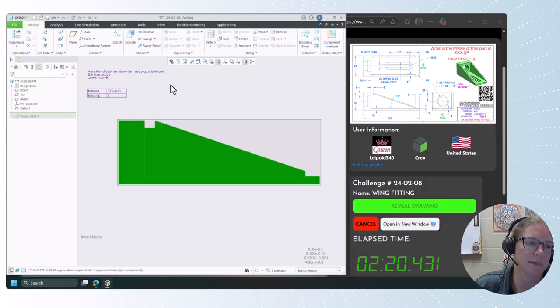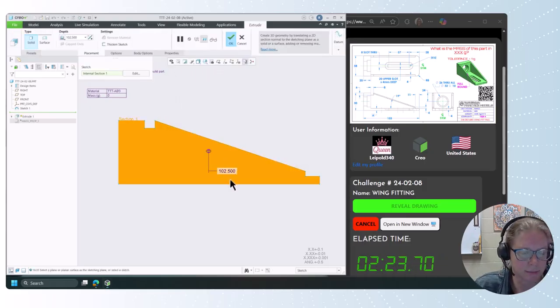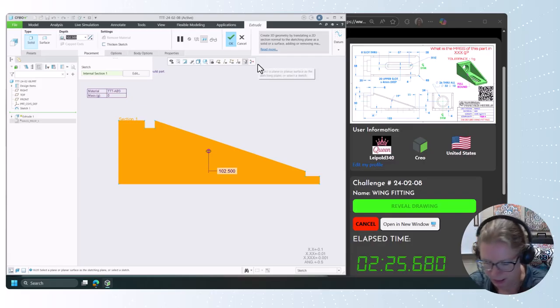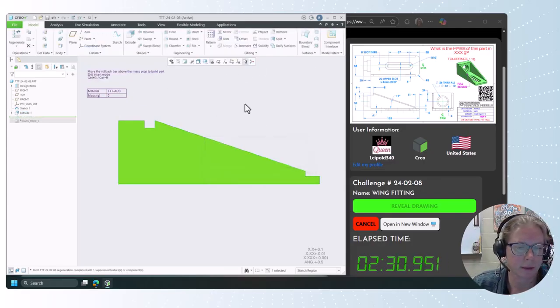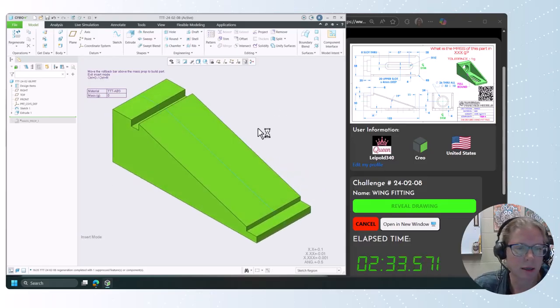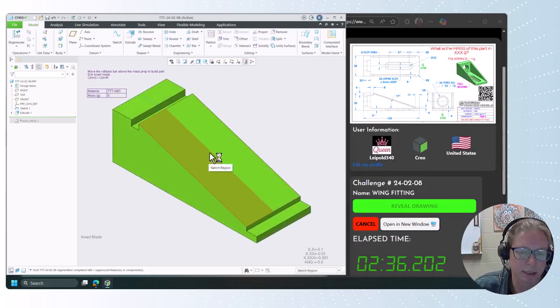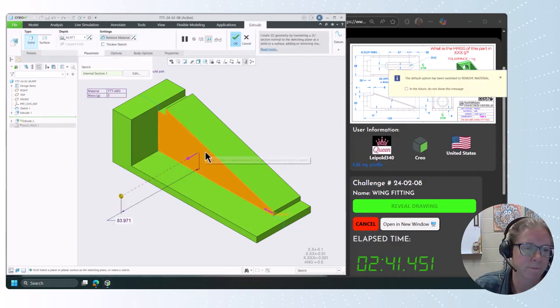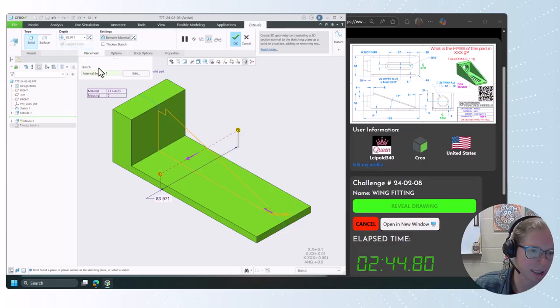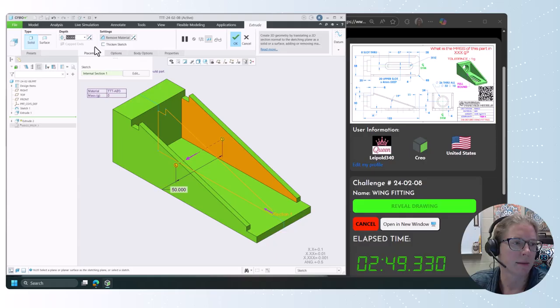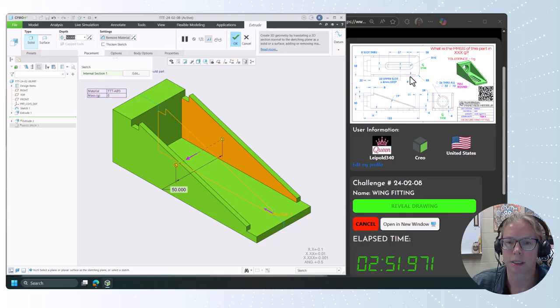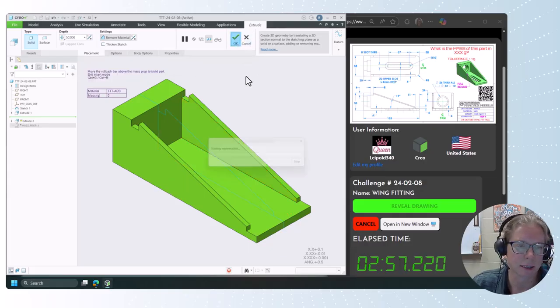We can select both of these faces and extrude that. That one's going to be the depth of 58. That value's in your top view. We do want this to be symmetric. All right, so I want to get this sketch region here, but I'm having a hard, well, hey, there we go. That's the one I want to extrude. We're going to make that symmetric, and we're removing material. And the depth of this is going to be 50. And that number comes from the 58 minus 4 here, and the fact that it's symmetric, so 4 on the backside. So 50 is our depth.